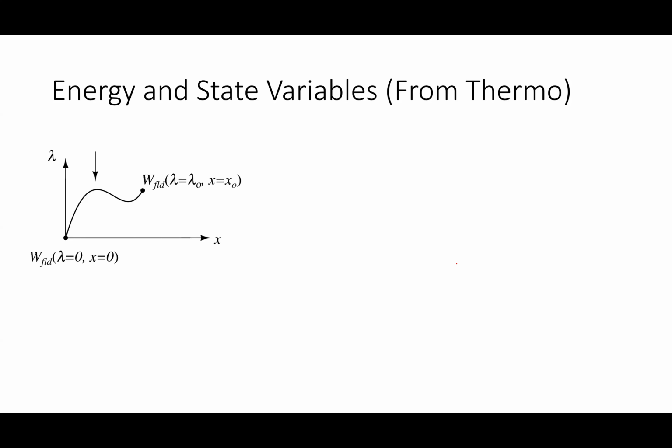If the thing can move, in this case, what we're saying is the energy in this magnetic system depends on two things. It depends on its flux, and it depends on its position. So what I wrote here, the energy is equal to I d lambda minus force dx. So x, the position of the thing, and lambda, if I know those two things, I can figure out its energy. You get into all this stuff about conservations, and I don't want to get too lost in the details, because we can get lost pretty quick. I want to jump primarily to the result of it.